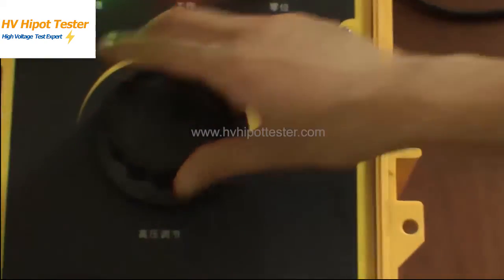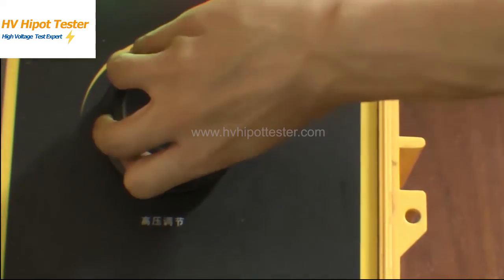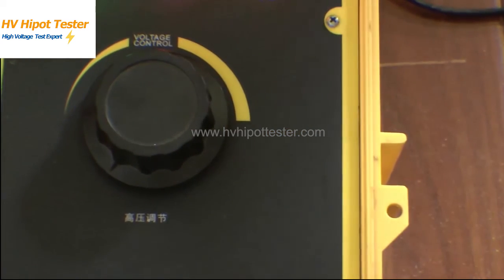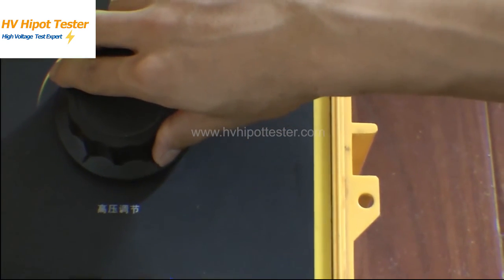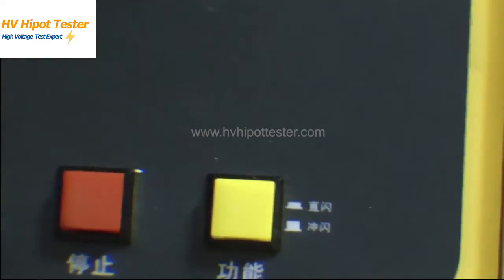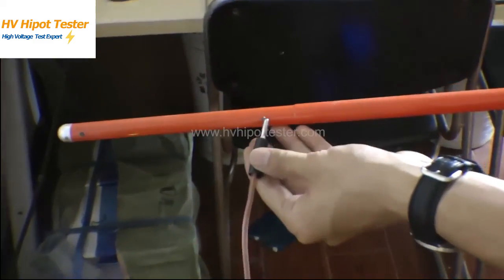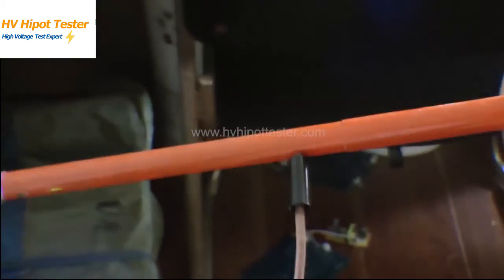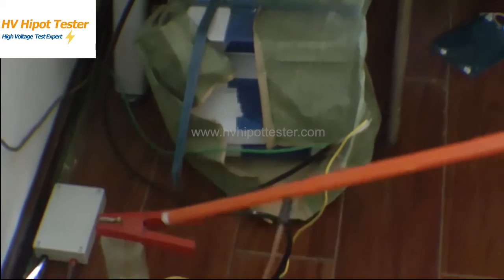Now we turn off the fault locator machine. At the last time of high volt discharge, turn the HV adjusting knob to 0 suddenly, like this. Press the stop button. Connect the discharge rod to discharge indirectly. This part equals a high resistance. Let's conduct current limiting discharge.